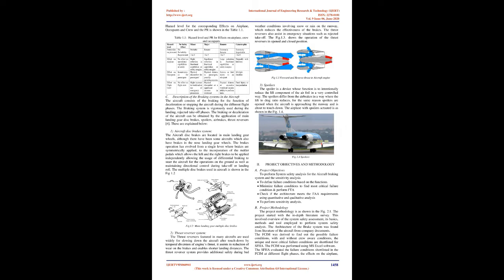Any changes to design cause changes to the system requirements, hence fault trees must be developed again. Once the design and architectures are finalized, the system safety assessment process verifies whether the implemented system meets the safety requirements. The failure modes and effects analysis, FMEA, is performed after the SSA for computing the actual failure probabilities onto the items. The verification is done by performing qualitative and quantitative analysis of the fault trees step by step, from the item level to the aircraft level after the integration of all the systems.